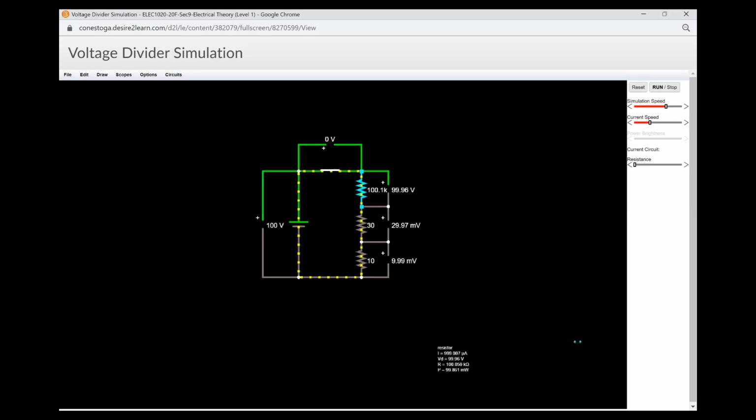When you check the simulation, you are just going to play with the slider here and crank it up to 10 megaohms. By having the 10 megaohms, you can see that by all means, we get full voltage, and it doesn't really matter what I do to that switch. Well, actually, this is not open, it's just 10 megaohms, okay?